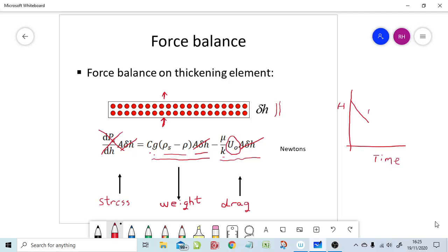So in that particular period we have just two forces, the weight force, which we always have, and the drag force from the liquid, and that means that by observing the height against time plot and taking the gradient of the height against time plot, that gives us the settling velocity. We can't do that though when we get to the curved section, and certainly not when it's nearer the stationary section. That's when potentially these forces come into play.